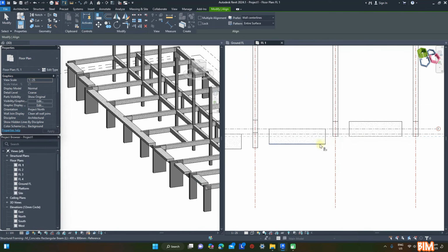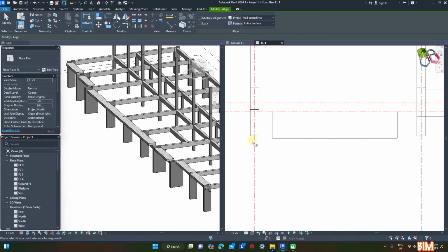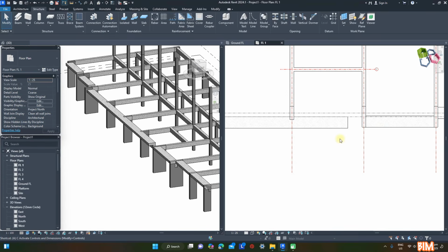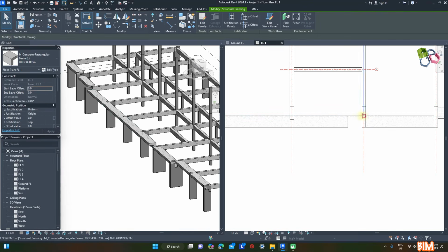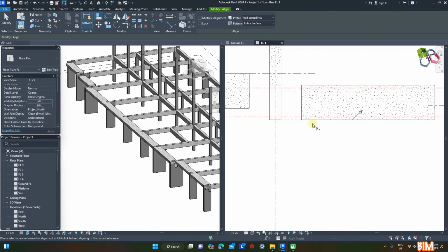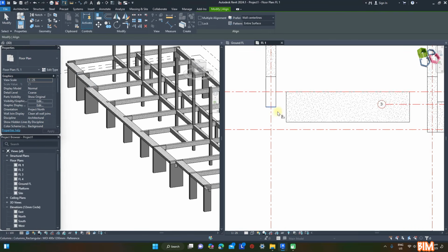Shortcut AL, to align the beam edge to the frontage column face. Lengthen the beam in between column positions. Install L beams to support the curtain wall at the frontage, all spans.